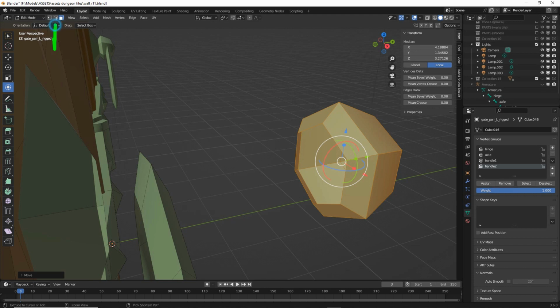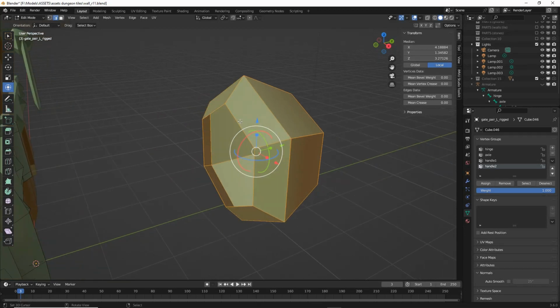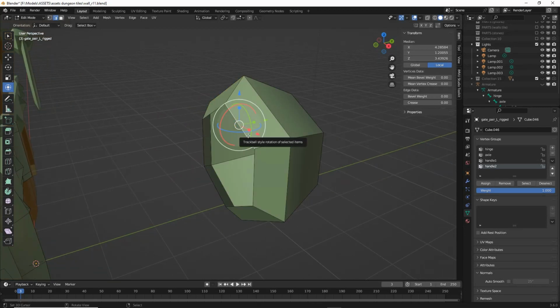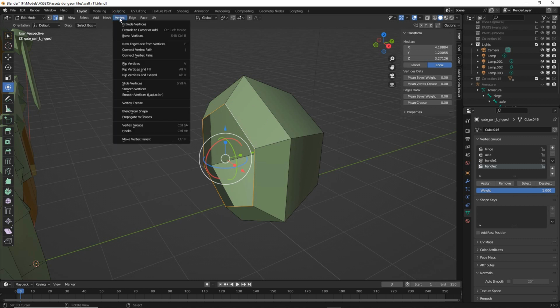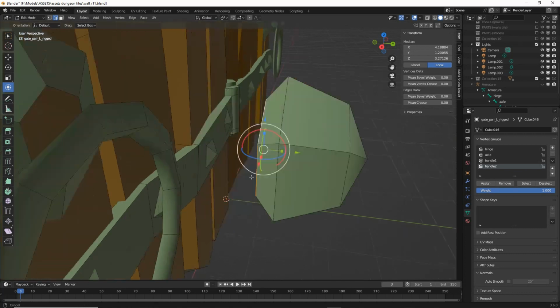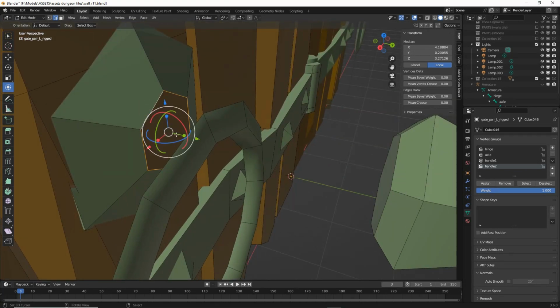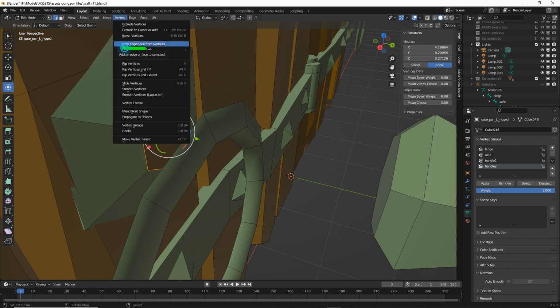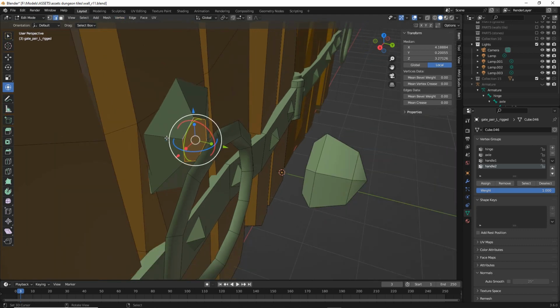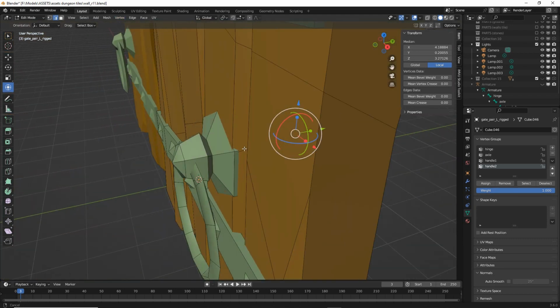And what that means is that we have to fill any open surfaces. So I'm just going to go into Edge Select. Loop Select, Alt Click, Vertex, New Face from Vertices. Same for the other side. Select, so that's Alt Click, Vertex, New Face from Vertices. That'll fill that. Do the same thing on the other side whilst we're at it.